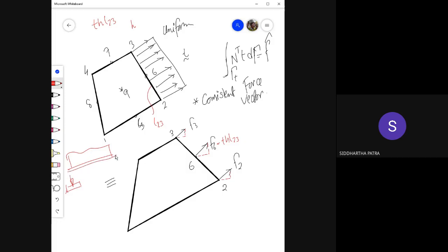The bar, let's say this is the distributed load, and it is acting on, let's say, yeah, it can be a beam. And when we want to think of where the resultant of all of these forces is acting, yes, obviously, that is acting in the middle. If it is uniform, it is exactly acting in the middle.